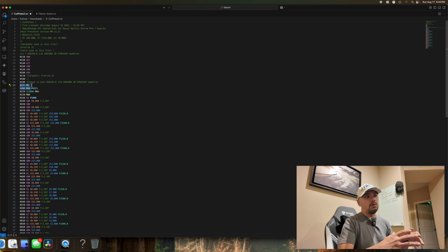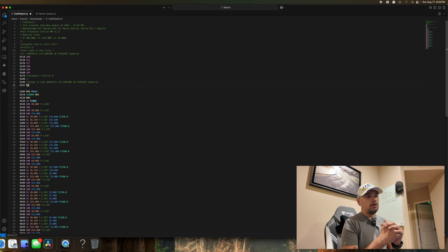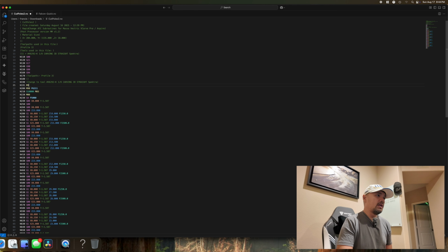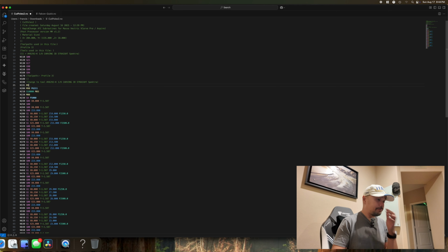The program will then retract the dustboot first before executing the tool change. If you need it, you can also add a delay to give the AutoDustBoot some time to fully retract before moving to the tool change, but usually M9 is sufficient. So this is one way to do it, but let me show you the better way.